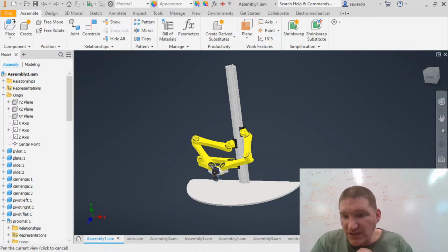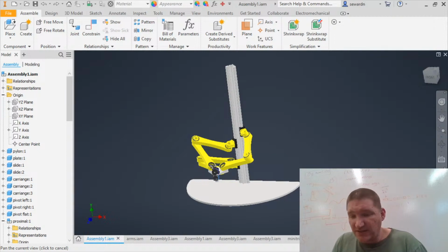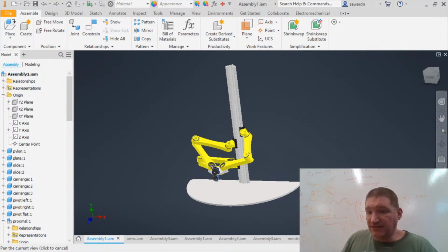You do not want to use stall guard with a lead screw. You could if it was a high enough lead screw and you turn the current down. So yeah, that's another thing: whenever I try to stall it and run it into an edge somewhere, you just got to turn the current down enough so you could skip steps and actually get it to stall. All right.